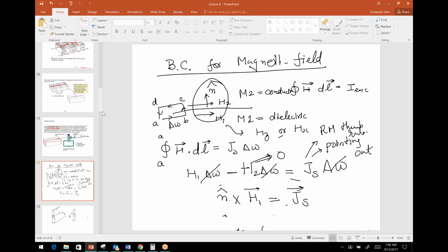So for most applications below 10 gigahertz, the approximation of conductors being perfect works pretty well for the wave shape and wave propagation. It doesn't work well for losses, obviously, because it will tell you that there is no loss happening, but we do see some loss.